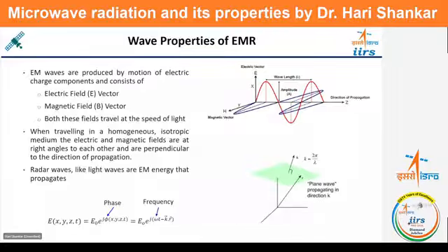Means first signal, let us say, was acquired before movement of the target, and second signal was acquired after the movement of the target. So this phi 1 minus phi 2 you can calculate. It means pre event and the post event phase you have. So post event minus pre event is called the phi 1 minus phi 2, or you can say delta phi, or you can say interferometric phase. So this phase difference equal to 2 pi upon lambda into path difference. So phase difference you can calculate from the phase images, and path difference you can calculate from this relationship.